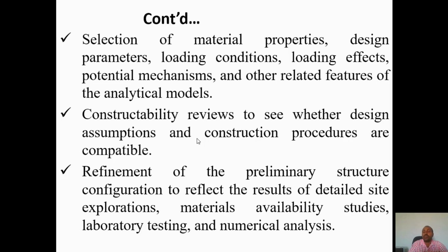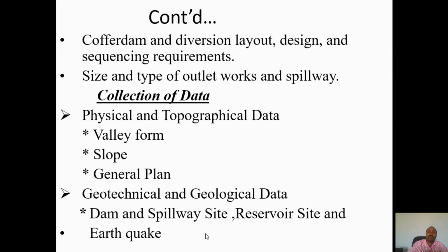And the last one, refinement of the preliminary structure configuration to reflect the results of detailed site exploration, materials availability, and also laboratory testing and numerical analysis. The other one is cofferdam and diversion layout design and sequencing requirements, which must also be checked. For the cofferdam, you may provide upstream and downstream cofferdams. Otherwise, flood may come.